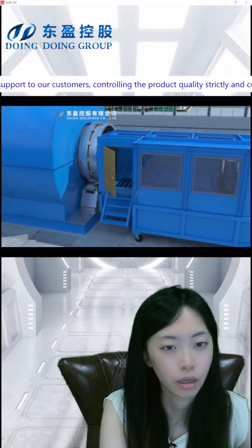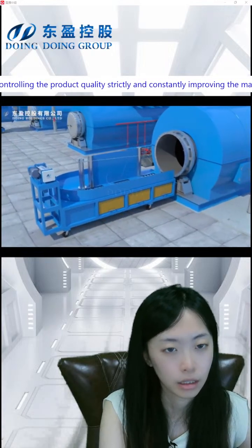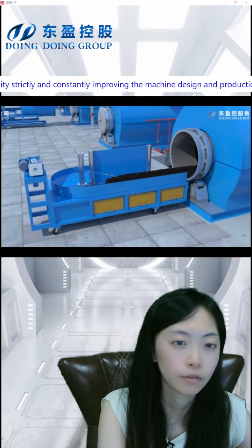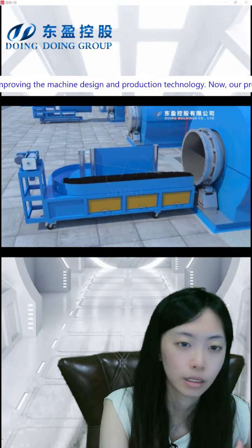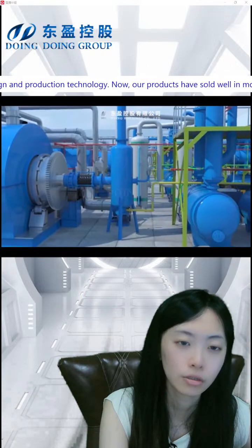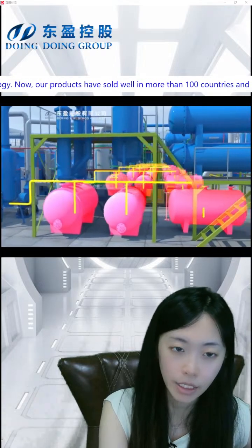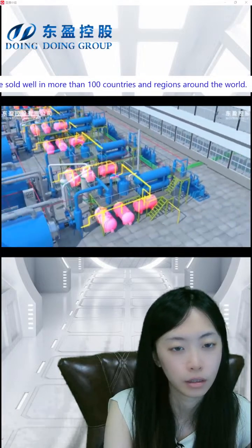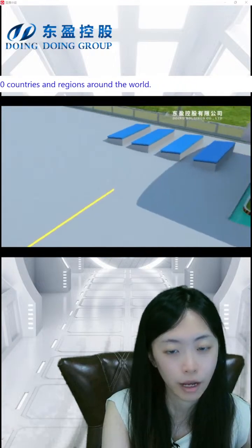If your raw material is different, the temperature to get the oil, the fuel oil, the oil gas is also different. For example, for plastic, the better temperature to get the gas is 180 to 220. This is the plastic. And if you have tire, the best temperature is from 280 to 320.